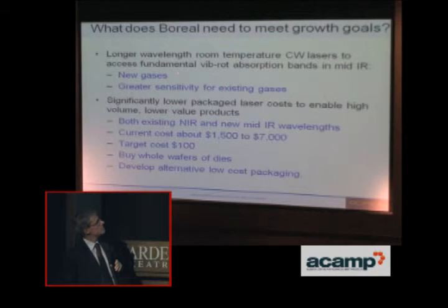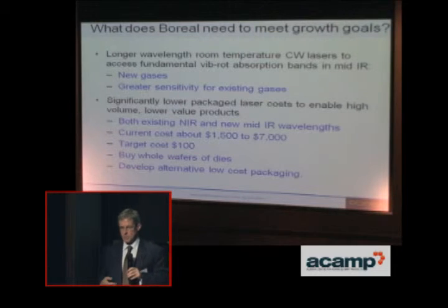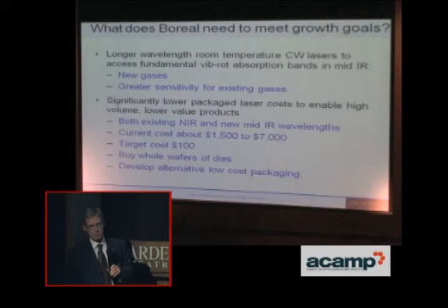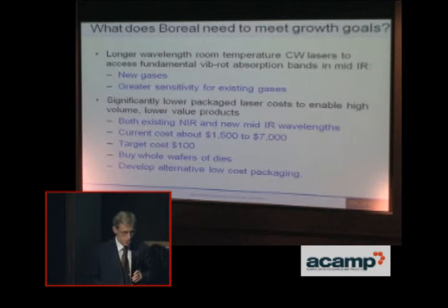Two different things. We need longer wavelength room temperature continuous wave lasers to access fundamental vibration rotation bands in the mid-infrared. We're currently working with weak absorption bands in the near-infrared. In order to access the really strong absorptions, we need to get into the mid-infrared, and that will enable us to not only access new gases, but get greater sensitivity for existing gases. The challenge